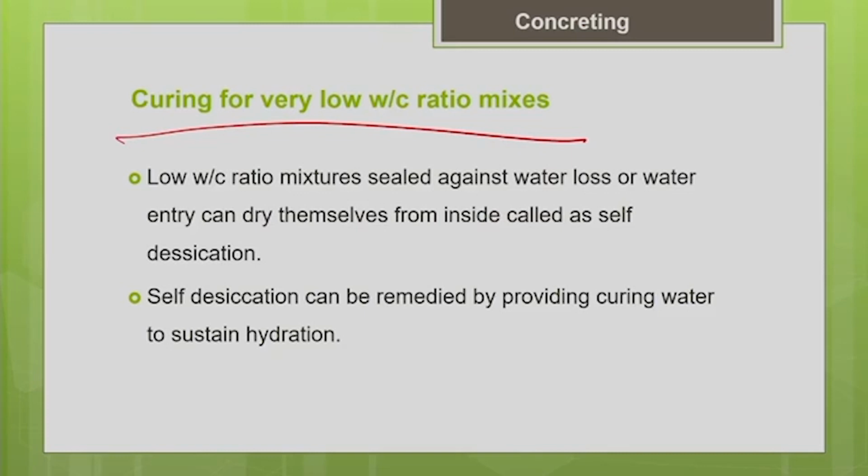So, that will be the best method, because what happens is, if you go for methods which just prevent the loss of water from within concrete to the outside environment, there are some water retention curing methods, which we are going to discuss later. If you are going for those methods, which just prevent the water loss from inside to outside, what happens is the internal drying of concrete occurs, that is called self desiccation.